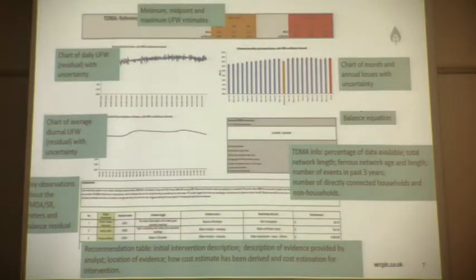And so this is a dashboard presenting some results, and I'm going to run through a few different examples from across 3 different companies of different elements of what you can find from doing these upstream balances, just to provide a bit of information. So I said at the start, it's not a DMA, so we're not only interested in the night use period, because fundamentally, if the flows are lowest through some of the meters at night, that's when they're likely to be most uncertain. So we can actually get a lot of valuable information from looking at the daytime period when flows are higher.